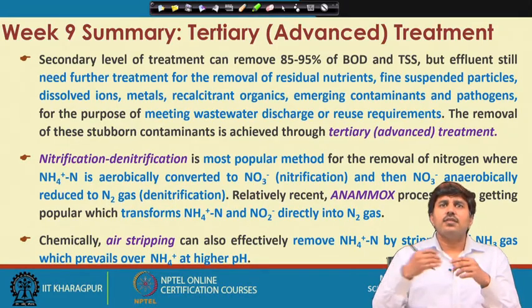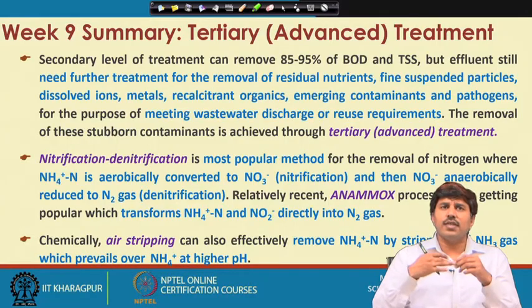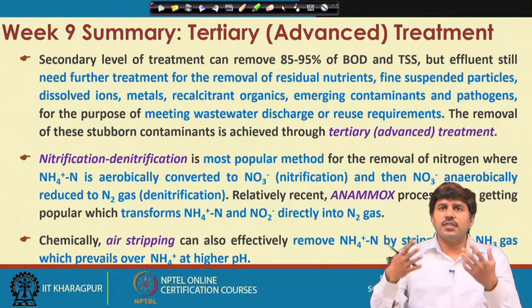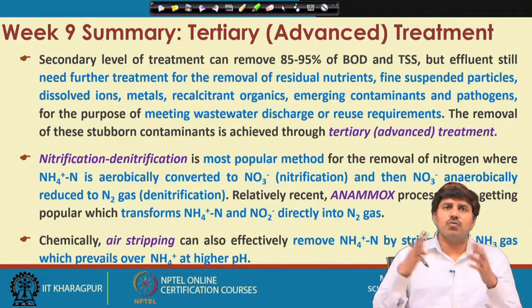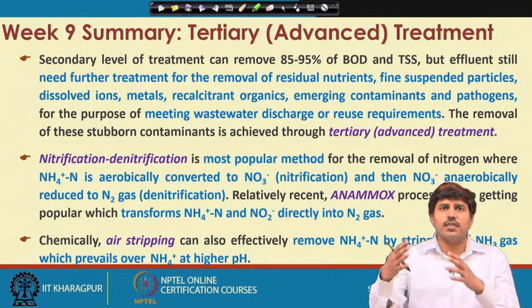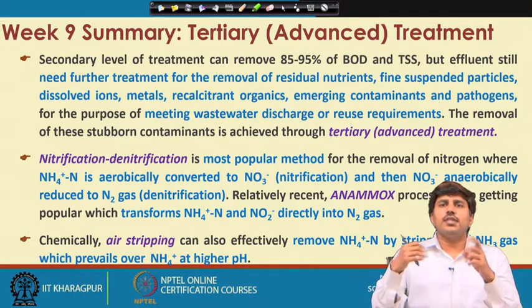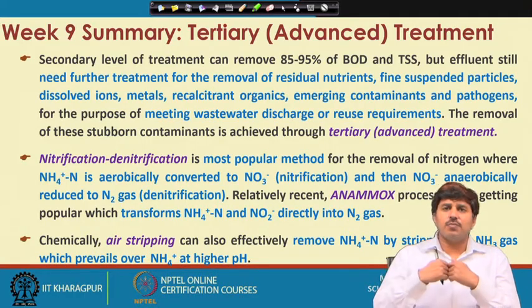These target the removal of residual nutrients, fine suspended particles, dissolved ions, metals, recalcitrant or non-biodegradable organic matter, emerging contaminants, and pathogens. Those are the things targeted for removal in the advanced stage of treatment. For removal of nutrients, we have biological as well as chemical processes.